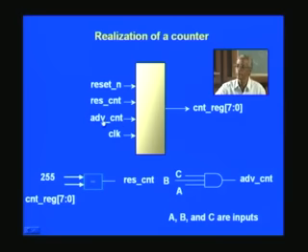Although it says advanced count, it is not a clock as such. The counter will be counting on the positive edge of the clock. Every time a positive edge of the clock is encountered, this will be counted, and this is the output we have seen here. And we have one more condition here, ABC as the enable for the counter as such, and once again ABC are inputs.